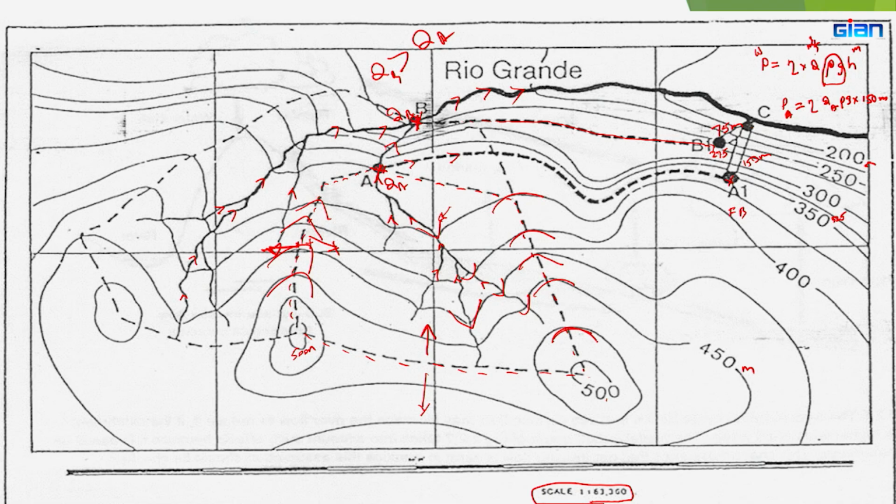And other hilltops you have to approximately guess, but the criterion is you judge whether rainwater falling at that location can come into your river system of interest or whether it goes to the other river system. Here we are looking at project A, therefore, we are looking at this catchment area. If the water falls here, we know that cannot come into our system.